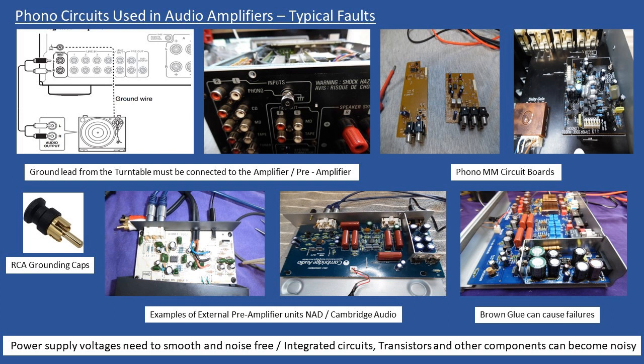So I trace through maybe to one of the inputs of the op amp, and I can't hear any noise, and then I look at the schematic and refer to the output pin of the op amp, and then if I hear electrical noise, it could be from the op amp, or it could be from a later part of the circuit. So then it's a very easy case to just remove the op amp, then go to the circuit point on the output again, and if the electrical noise is gone, that really tells me that the op amp is the cause. And you can do that also with the transistors, the same thing.